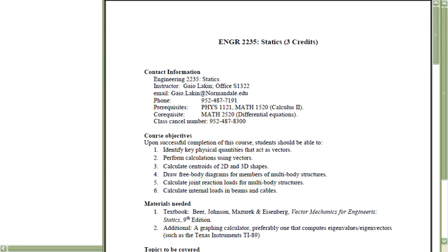So you can represent it just with a scalar value, but really in 3D, moments are vectors just like forces are. And so when we do Newton's second law, that's a vector equation. When we do the rotational version of Newton's second law, M equals I alpha, that's also a vector equation.